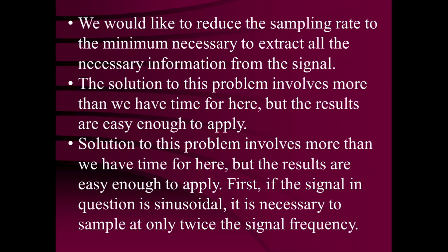First, if the signal in question is sinusoidal, it is necessary to sample at only twice the signal frequency. So what is important? If the signal in question is a sine wave, then the sampling rate need only be twice the signal frequency.